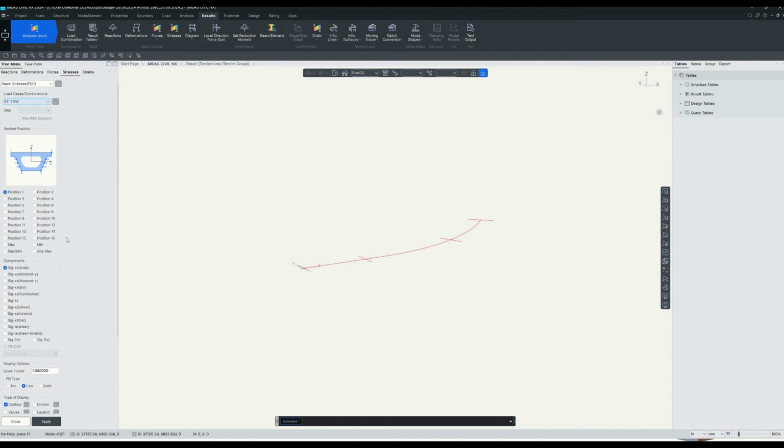Now I'll show the stress state at each stage of construction. For example, construction stage 2. To check the stresses, we need the summation effect. This summarizes a number of effects. The set is always different for reactions, forces, and deformations. These are primary and secondary effects of pre-stress, and the secondary effect of creep and shrinkage. In the future, we will need this separation of effects.